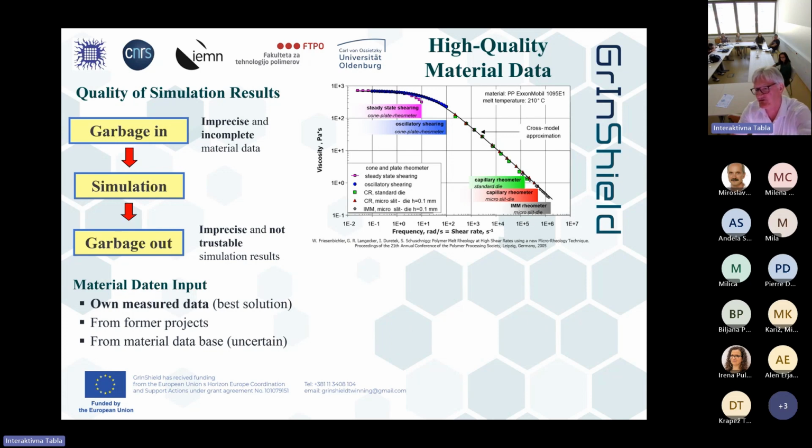If we have such a gap, the approximation software doesn't know how to make a curve through all the measured points. The computer doesn't need measured values. The computer needs an approximation curve, which we call a material law. It's part of a so-called material card where all our testing results are in. And with that, we can nicely characterize the flow behavior.